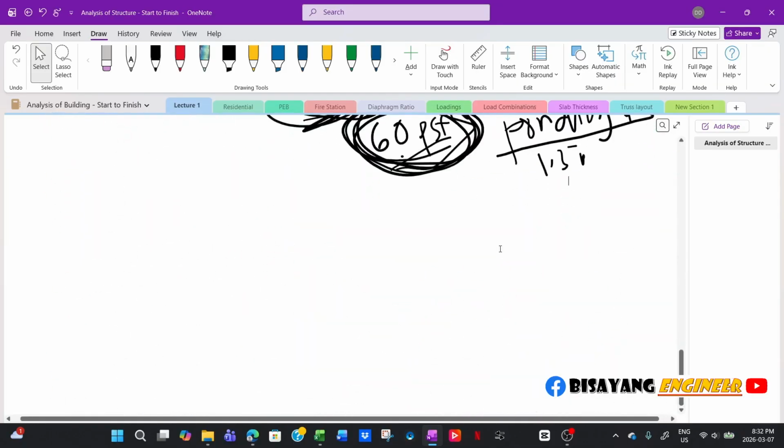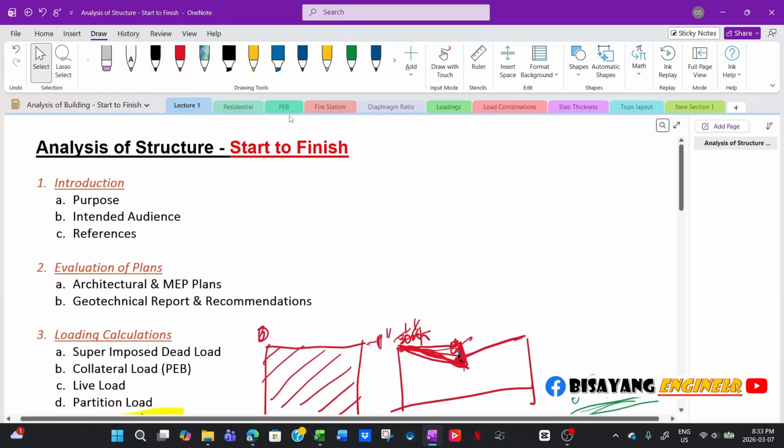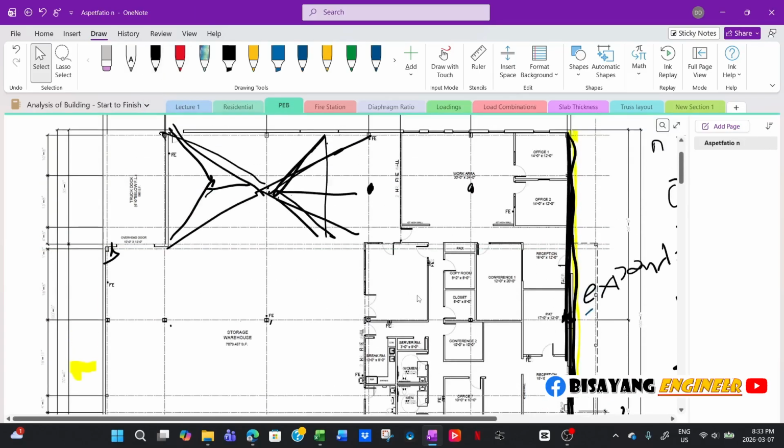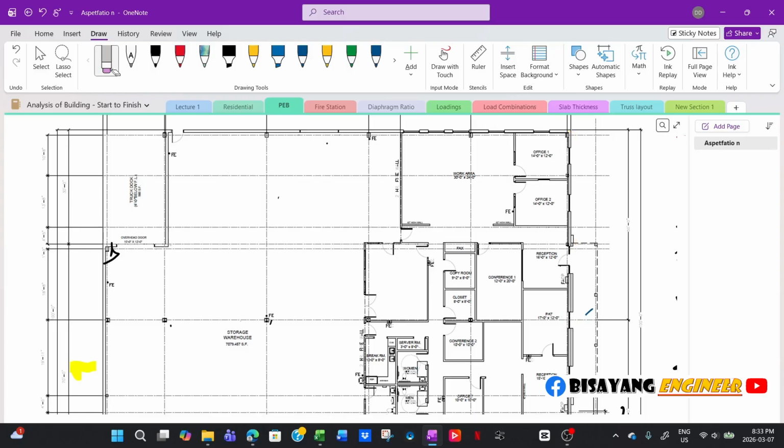In the framing plan, you have to show the actual ponding load now, because if you are not the one who sizes the trusses, so for example, typically most engineers of record of the building will just show the roof framing plan.